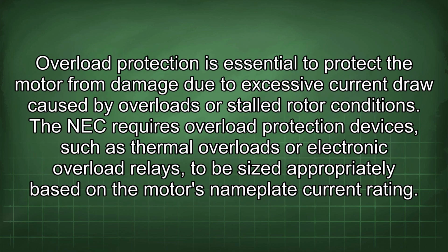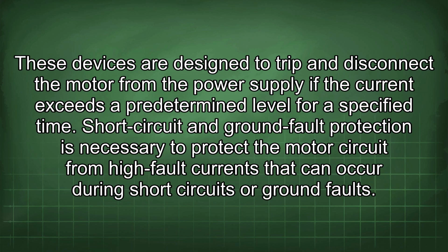Overload protection is essential to protect the motor from damage due to excessive current draw caused by overloads or stalled rotor conditions. The NEC requires overload protection devices, such as thermal overloads or electronic overload relays, to be sized appropriately based on the motor's nameplate current rating. These devices are designed to trip and disconnect the motor from the power supply if the current exceeds a predetermined level for a specified time.